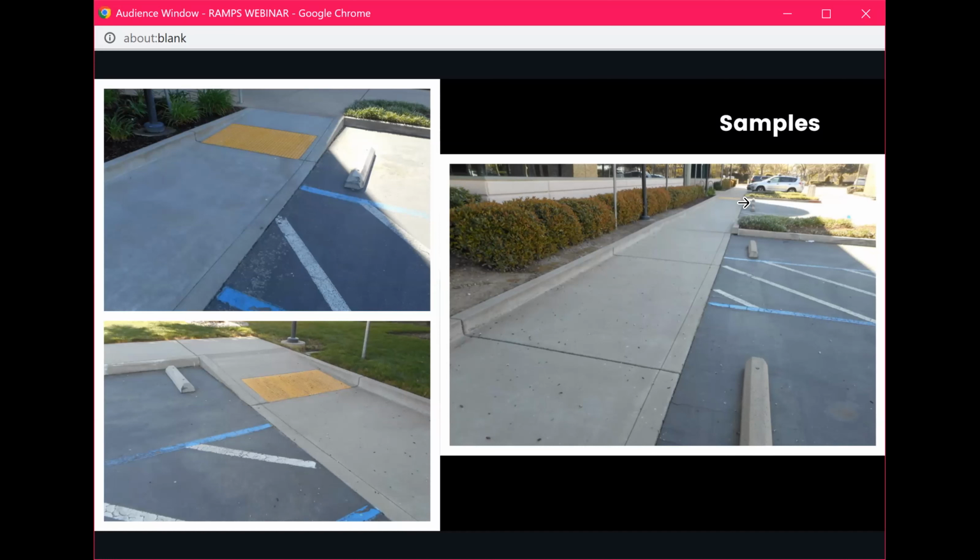Wouldn't it always be for both able-bodied? I mean, anybody can use this. How do you distinguish? There's an exception, I think exception 3, where if the path is exclusive to accessible stalls, you do not have to have detectable warnings. You have to have it where the raised path meets that accessible path only.